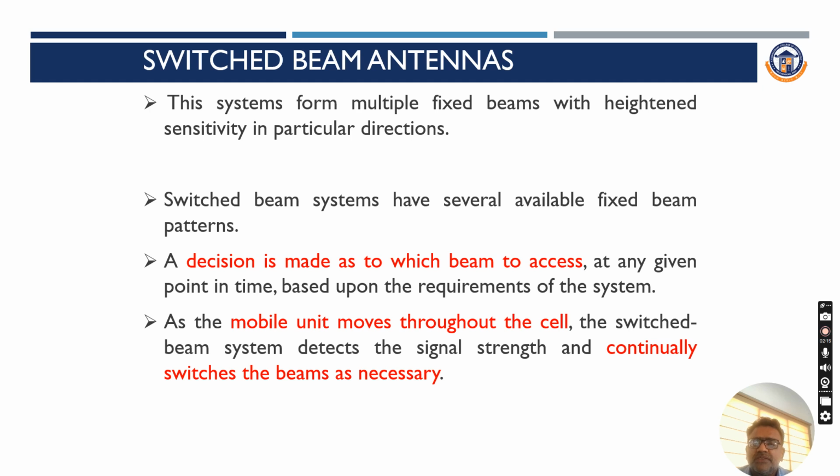In switched beam, this system forms multiple fixed beams with heightened sensitivity in particular directions. Switched beam systems have several available fixed beam patterns. A decision is made on which beam to access. Whenever there are more users at a particular location, that particular beam will be accessed at any given point of time based upon the requirement of the system.